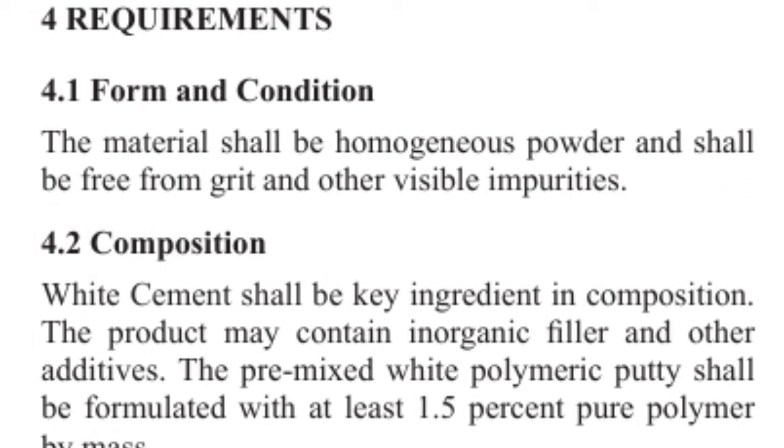Then what is the composition? White cement shall be the key ingredient in the composition. The powder may contain inorganic filler and other additives. The premixed white polymeric putty shall be formulated with at least 1.5% pure polymer by mass. So these are the composition guidelines that the IS code has given, which you should follow. And what is the consistency?